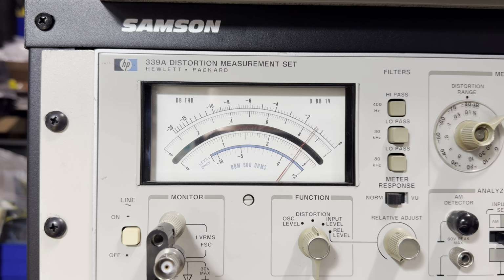I am trying to cover some of the concepts here as we go forward in this series. Talking about distortion analyzers, talking about signal sources, and how the two play in together to make a distortion measurement set, both our source and our analyzer. Our measurement floor is ultimately going to be limited to the performance of our measurement system. If we have a better source, we can take a better, lower measurement.